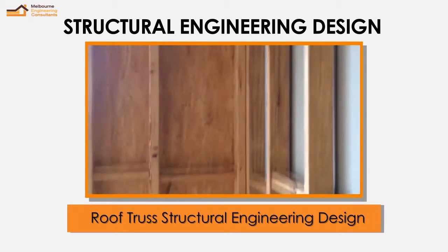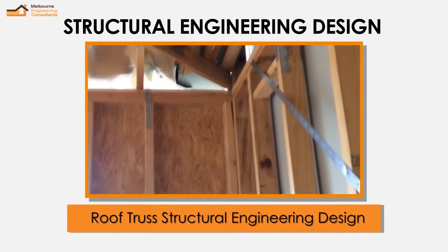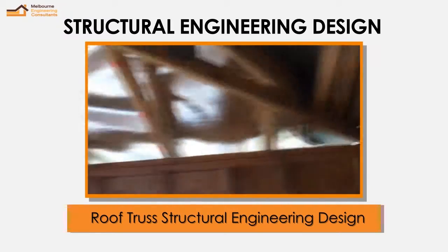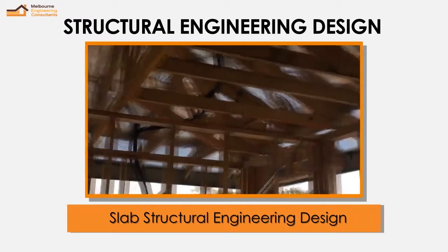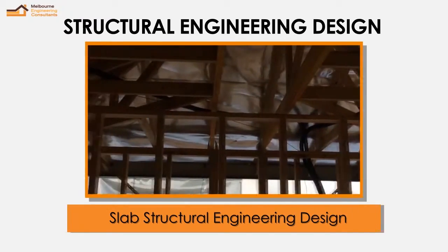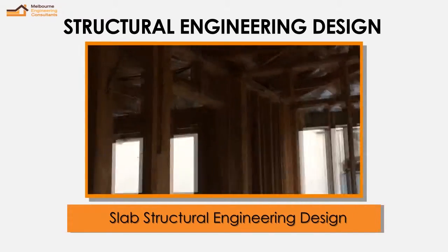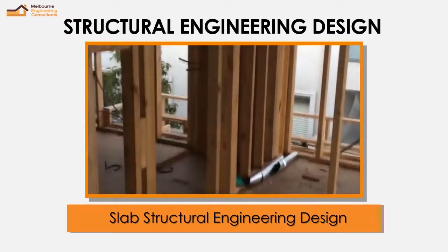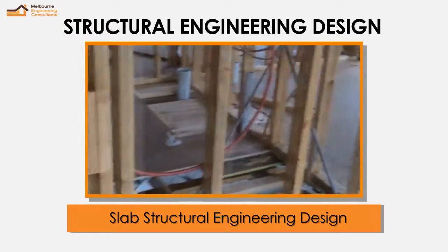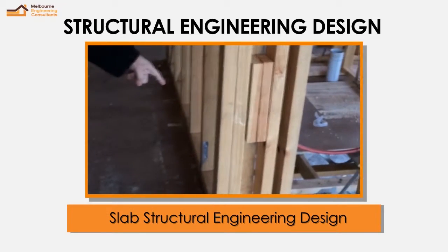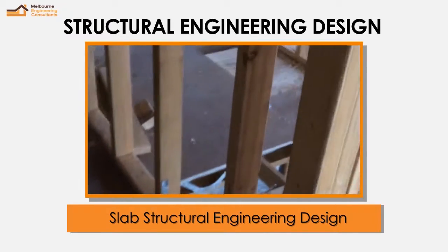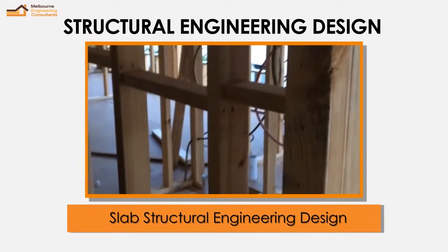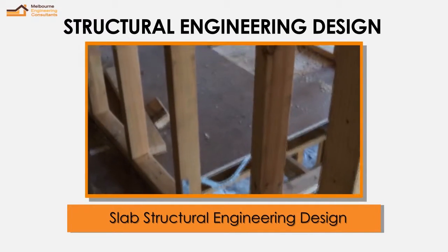So this is a big lintel sitting on the other side on double studs. That's why we save money on the projects. Here is again the corner bracing, which is hardwood, and this is a stud wall with a D-brace, strap metal, another wall here, and this is showing the posts, because it's still under construction. So we are showing two posts here, sitting at 40 centres with a steel beam.